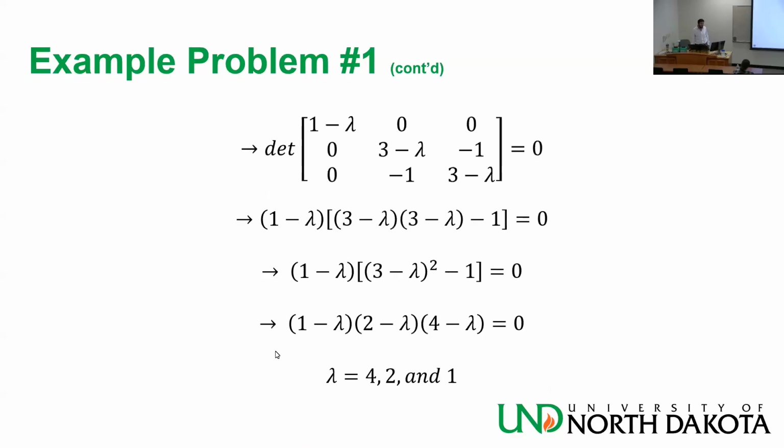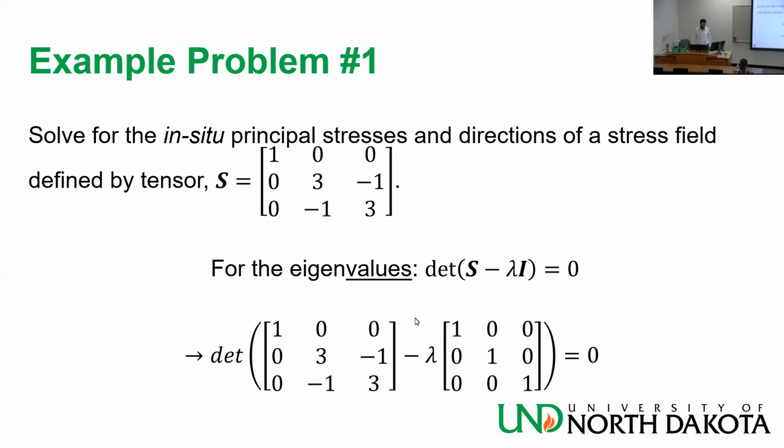I expect you to know how to do eigenvalues and eigenvectors, but don't expect something crazy, because remember we said that for stability in the Earth's subsurface, the stress tensor must be diagonally symmetric, which makes our math a little bit easier. In homework 1, all the tensors I gave you were unstable, so they were harder than they had to be.